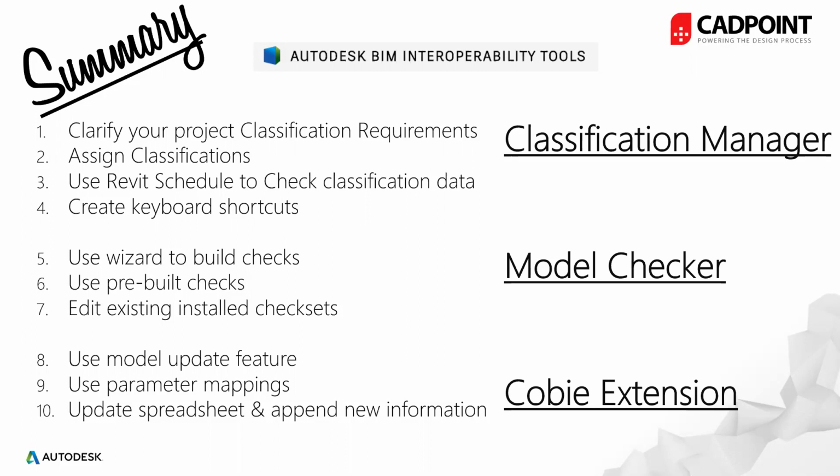Okay, so on BIM level 2, or now BIM framework projects, as it's now known, some sort of classification is required, yes. The BIM interoperability toolbar only assists you in putting that information together. It just makes it a bit easier. You don't have to use that plugin by any means. People may have other methods of doing it, but if you're doing it from inside Revit, it is one of the most efficient ways, purely because you can link your Revit parameters to the actual classification parameters.